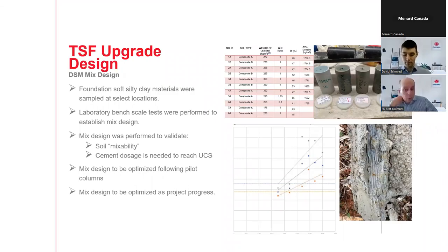That's a very important thing to notice when you do your design: it needs to accommodate some of that variability, which is inherent to any soil mixing job, because you have different soil profiles and different water content, and this will affect the end result of what you'll be mixing.